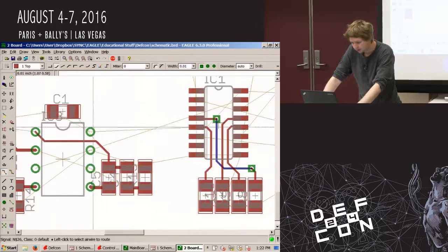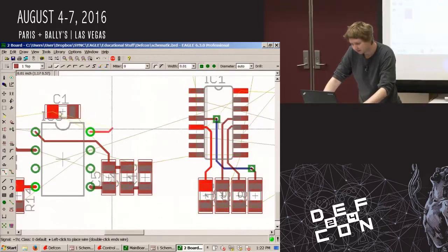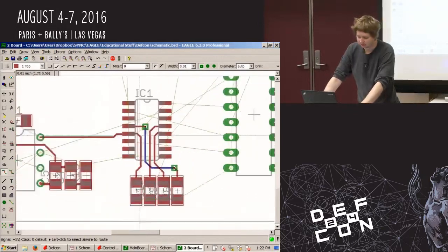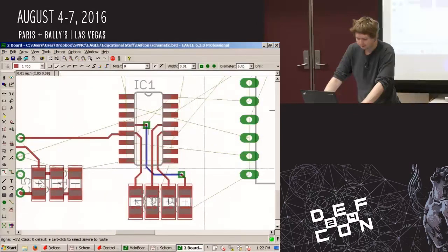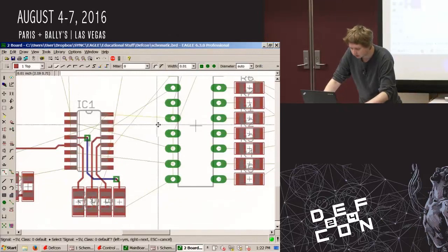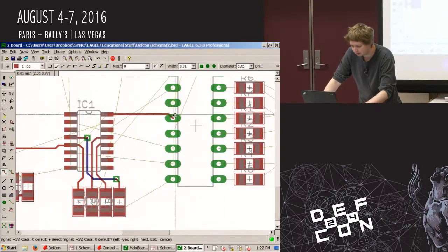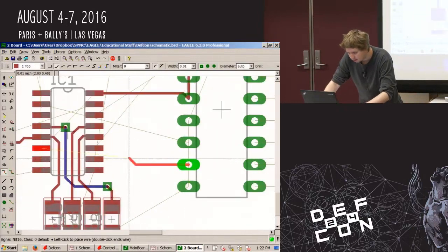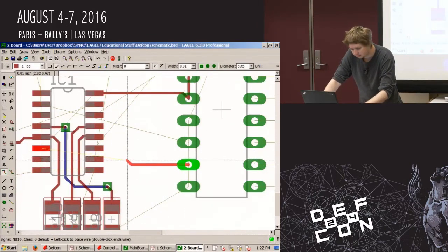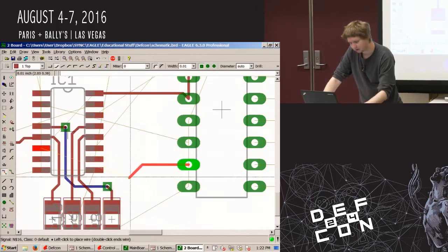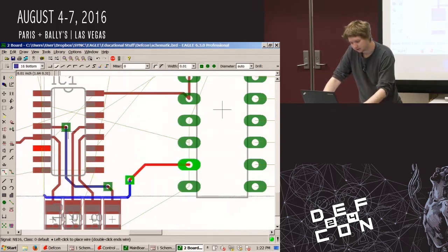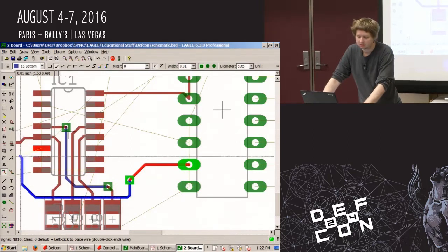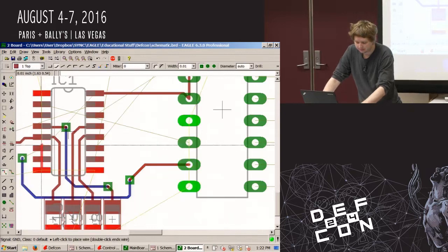All right, so the clock from the 555, I needed to go into this chip here, and I'll actually go ahead and also just connect it up to this type of stuff right here. So run another via. I have to go underneath all of my bottom layer right now.